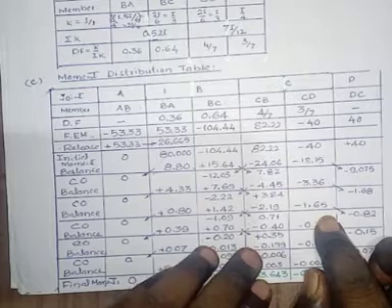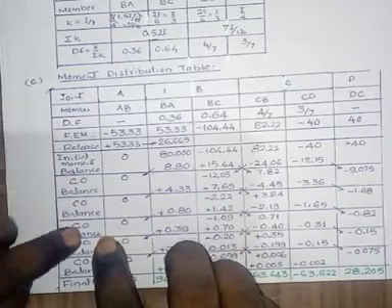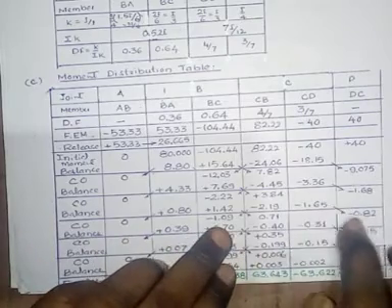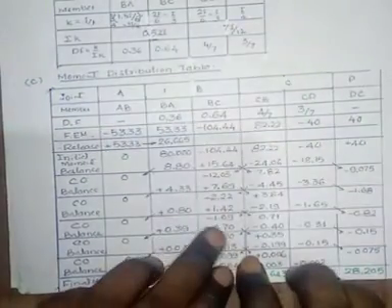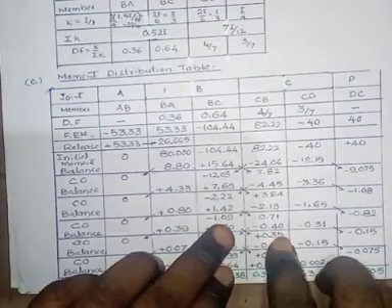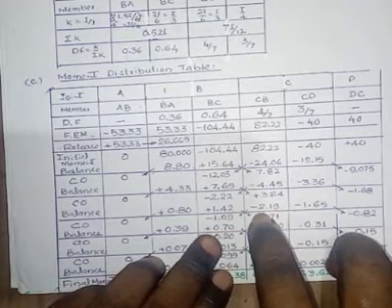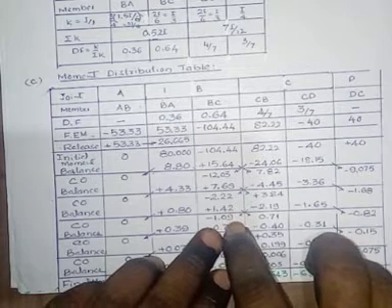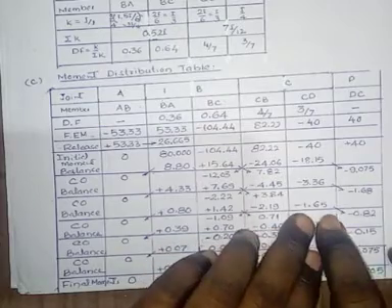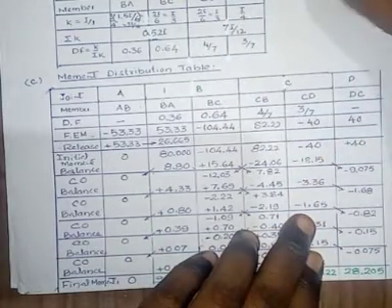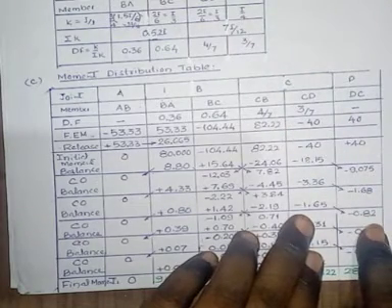Again in the next cycle, that is 1, 2, 3, in the fourth cycle, we have to carry over 50% of the moments. Here there is no carryover since this end is discontinuous or non-continuous. B to C, there is carryover, that is half of 1.42, that is 0.71, half of minus 2.19, that is minus 1.09, with the same sign it is carried. Then minus 1.65, half of that, minus 0.82, is carried over towards D.